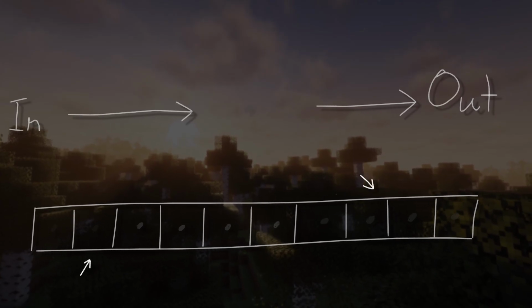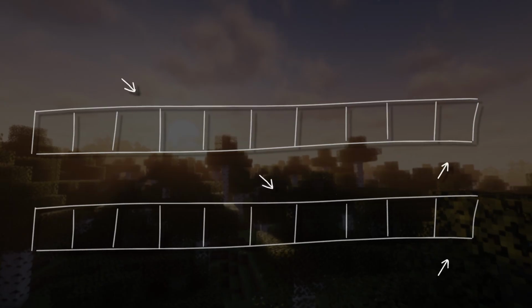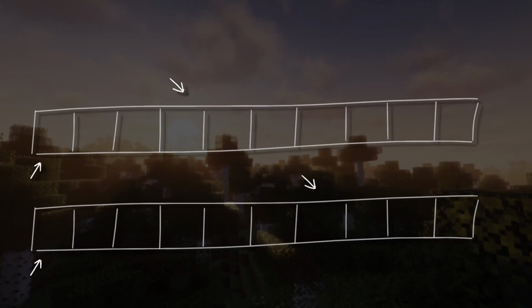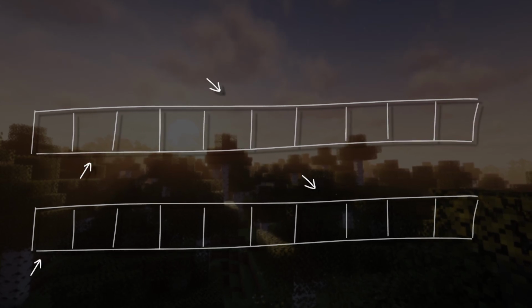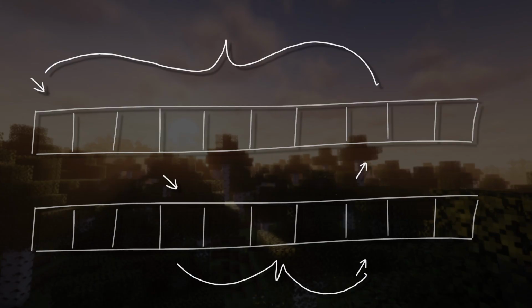To get a reverb sound, we need to mangle these echoes and make them repeat fast enough so that it sounds more diffused. If we had multiple channels, each of them having delays that vary in length, for simplicity, imagine each channel has a slightly longer delay time. The sound gets more complicated and these echoes sound less distinct or separate because there's, well, way more of them. To have this vary in delay time, we simply just have a different separation sample number between the read and write pointers. This separation specifies how long the delay would be.